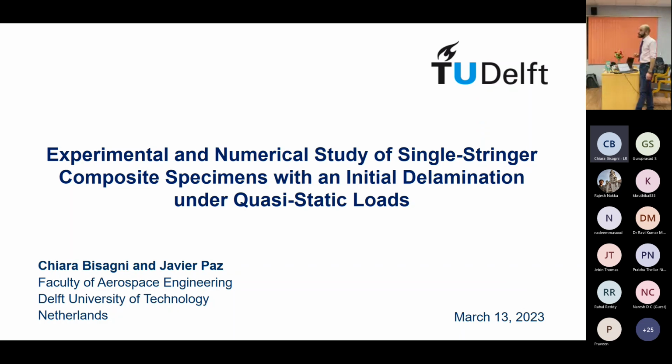The one we use is from Correlated Solutions, and it always gives you a suggested subset size. So you take that as a starting point. But then one of the metrics that you can retrieve with digital image correlation is what they call the sigma pixel, which is the predicted error at that location for the out-of-plane displacements, for strains, for whichever metric you're looking at. So there's a bit of an iterative process in there.